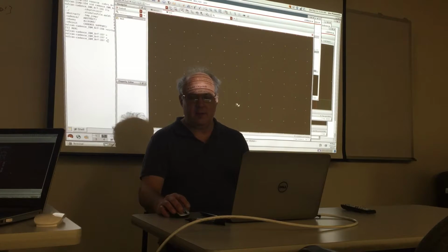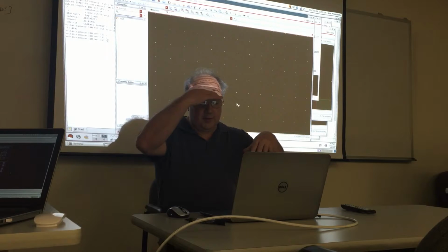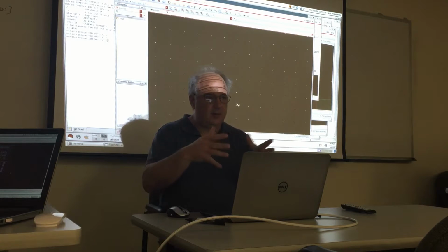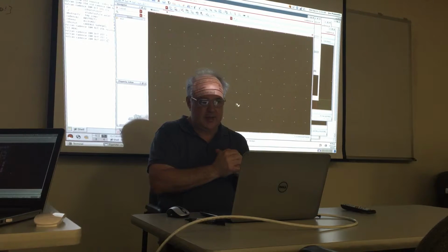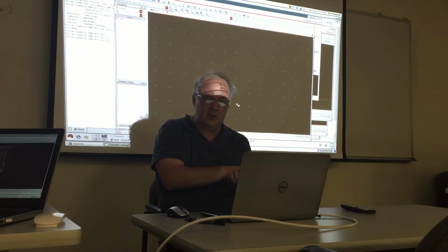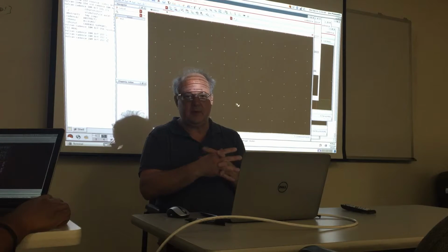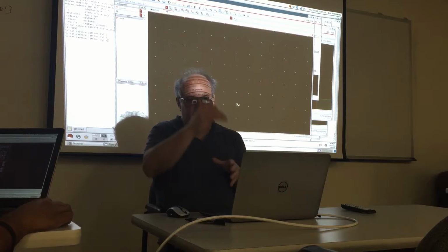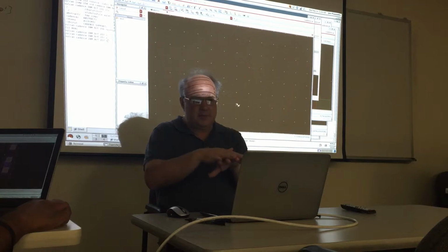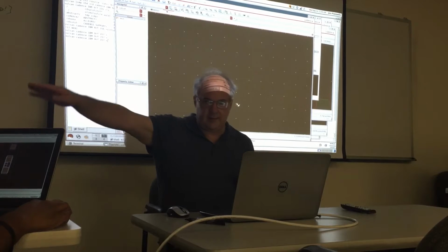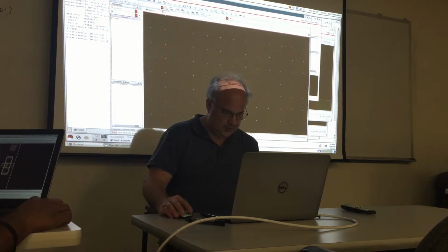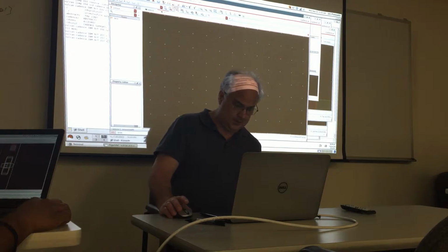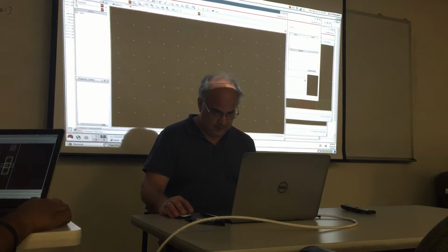Oh, by the way, I forgot to show you in the DRC. We'll do it when we do the LVS. Once you get it pointed to the right file, you want to save the run set as something local in your Cadence IBM 9RF directory. I create a directory called Caliber, and I have my three run sets in there. Most of what's being stored is just the path out to the IBM file. There are some other options, especially for XRC for extraction. I have several run sets for XRC because I want to do different extractions for different reasons.